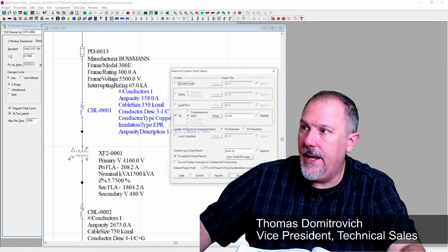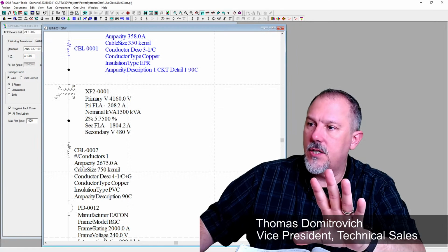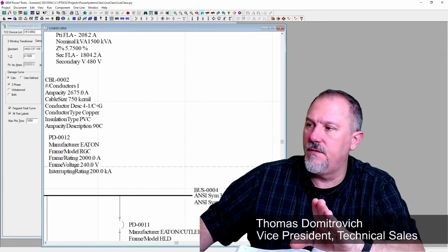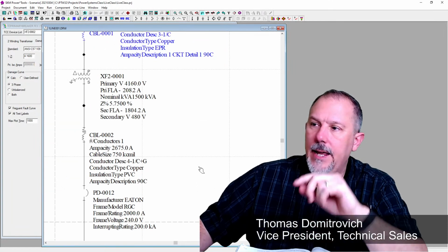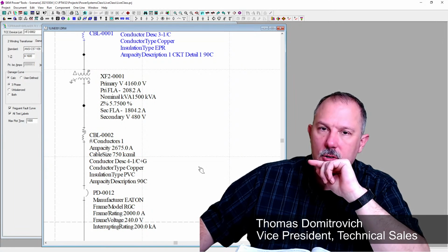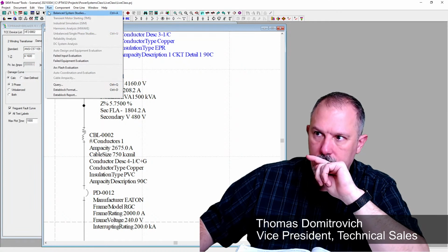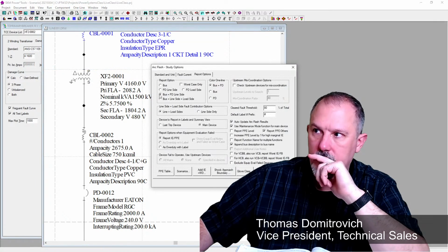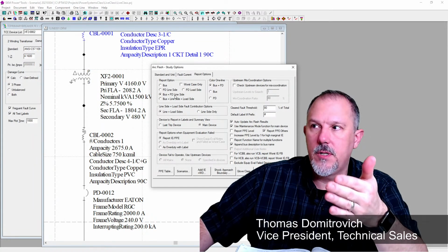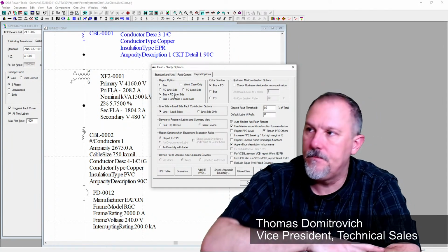Let's do a control A just to do a run. I make sure that all of that's correct. So I know I have a 29,000 amp, almost 30,000 amp bolted fault current here. And I'm going to run an arc flash analysis. So let's do that. Let's run arc flash. I'm going to pick bus plus protective device line side. So it's the line side.